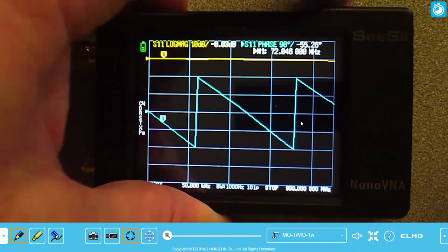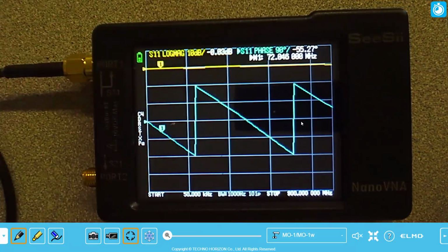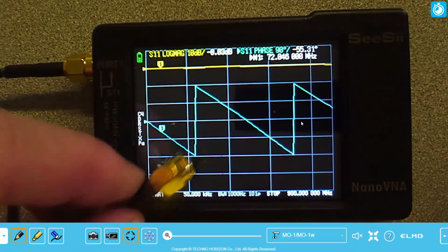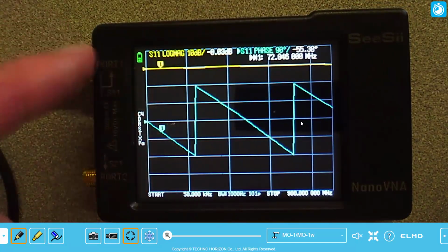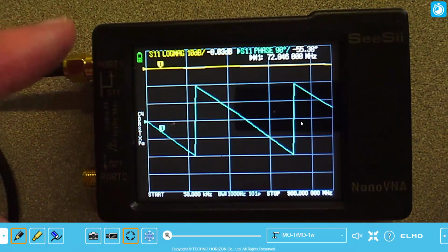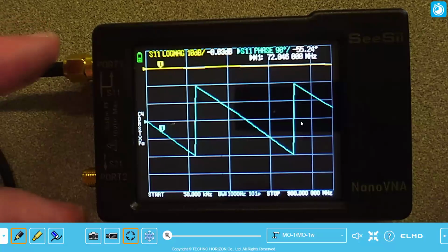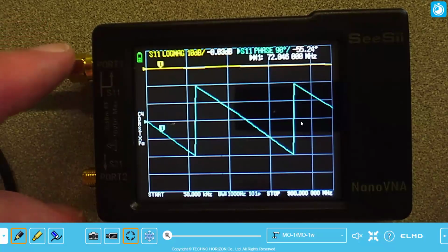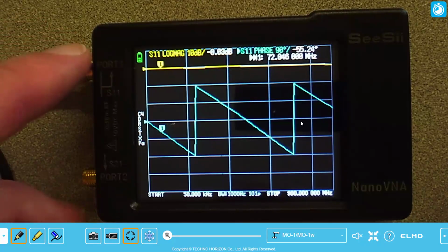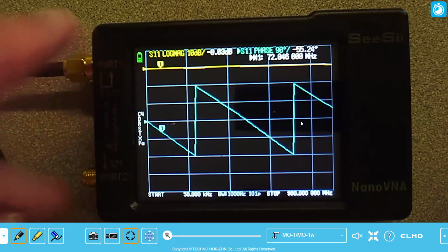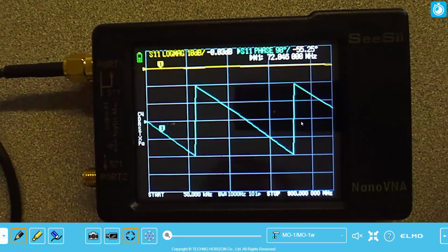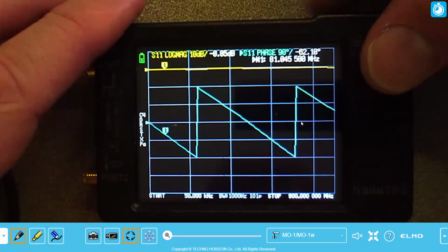So at 0 frequency, there's no phase shift. And as we go up and up in frequency, the wave goes down the coax, off the open circuit and back in. So it propagates the length 2L of the coax. So it picks up a phase of 2 times the wave vector beta, or k, times L. And beta, the wave vector, is 2 pi over lambda. So it picks up a phase that's proportional to the frequency. So as we go up in frequency, the phase gets more and more and more.